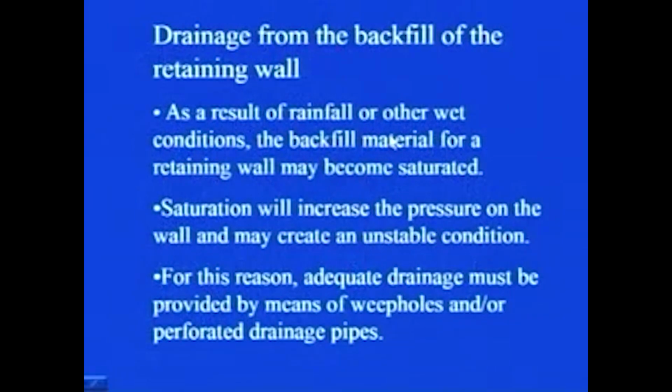So, let us discuss some aspects of this drainage. If there is a rise in water table, then pore water pressure will get generated, and if proper drainage facility is available, this will get drained out and there will not be any development of pore water pressure. So, let us see the various aspects of this drainage and how you can facilitate this drainage in the backfill part.